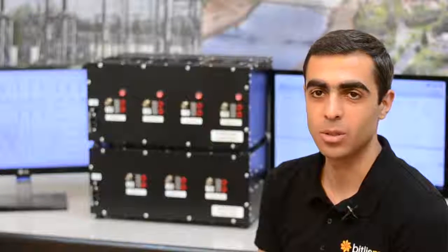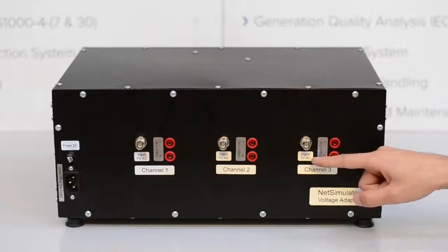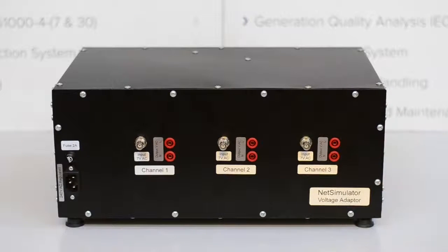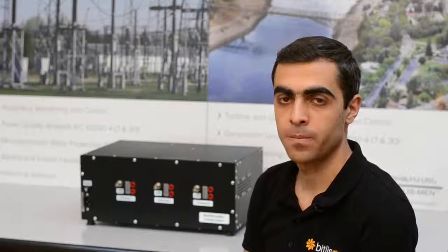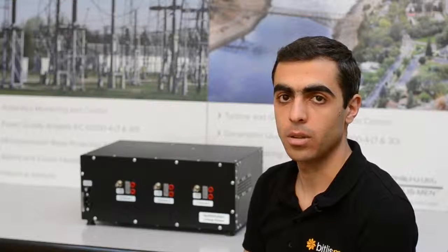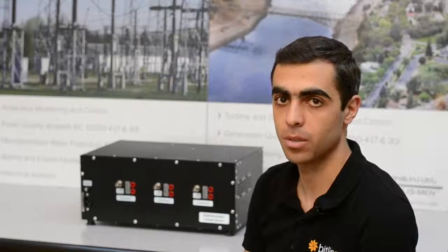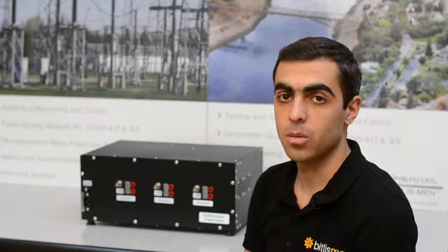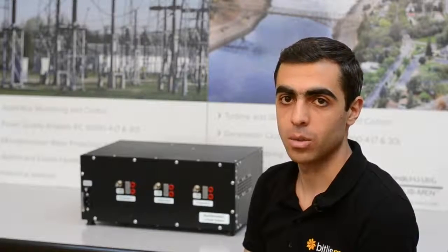Now let's have a look at the voltage adapter. The input accepts 7 volt AC or DC signal, and the output ranges up to 220 volt AC or DC. The adapter converts the input low voltage to high voltage signal. The conversion is done transparently, meaning the high voltage signal will replicate the low voltage signal shape and spectral band up to 64th harmonics within 1% error. The voltage adapter is intended to be used only with measuring devices which have high input impedance. This means the output of the adapter cannot be connected to a load.